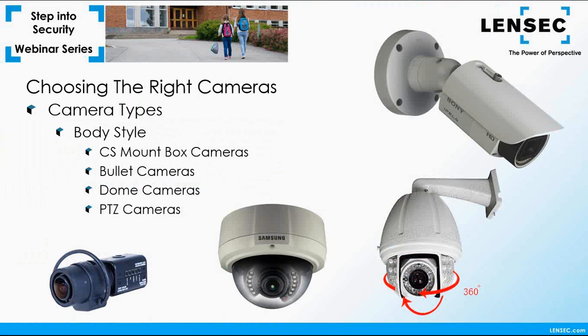Here are several different types of camera body styles that can be used in different scenarios. On the bottom left, we have a CS mount box camera. The letters CS refer to the mount for the lens that is interchangeable on the camera. This type of camera is usually used indoors or in a camera enclosure for outdoor use. These are popular if you have to change the lens on a camera to a non-standard focal length.